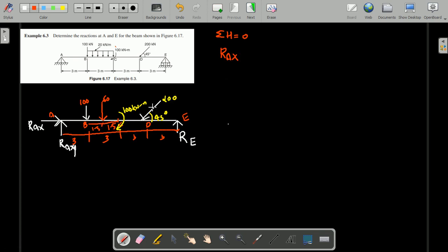One inclined force is there here, 200. So we know the resolution. If 200 is an inclined force, we are resolving this force into two components. Horizontal component becomes cos because it is making an angle 45 degree with respect to horizontal. Therefore 200 cos 45 is your x component, and 200 sin 45 is your y component.